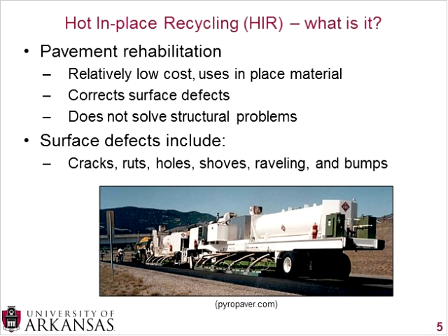So what is hot-in-place recycling? Well, it is a pavement rehabilitation technique. It is relatively low cost, and one of the reasons for that is it uses a lot of in-place material, and that saves costs for shipping aggregate, hot mix, or concrete from some off-site source to the job site. And it can correct surface defects, such as cracking, mild rutting, mild shoving, those types of surface defects, but it does not solve structural problems.